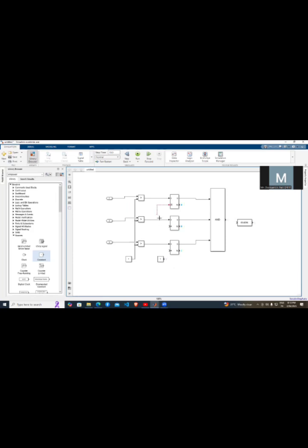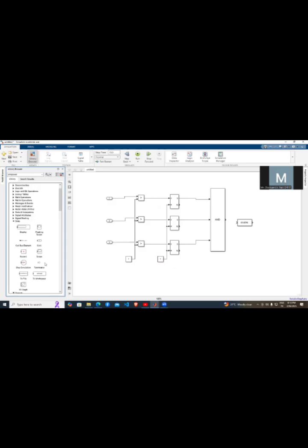Okay. Similarly, we will connect the block like this. Now there is one terminal left at the SRP block, so we have to terminate that. We will require the Terminator function. Go to Simulink, then Sinks, and from the sinks you will find the Terminator. So Control C that.